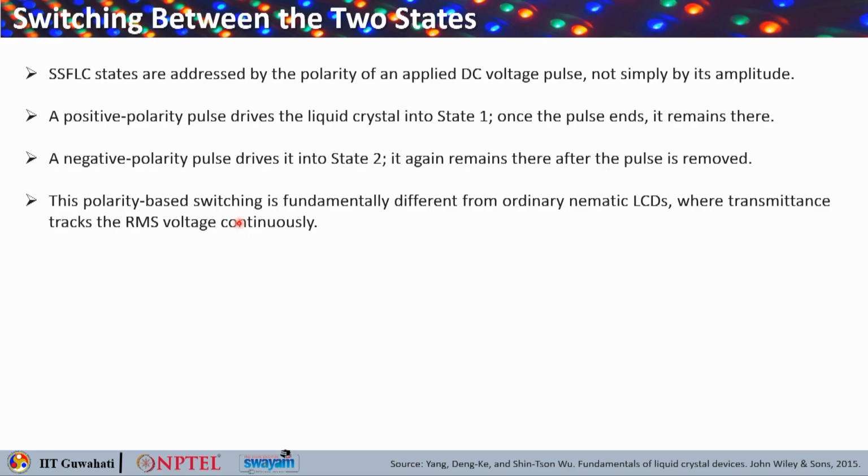So, this is basically polarity-based switching, not amplitude-based switching, okay, and this is fundamentally different from the ordinary nematic liquid crystal displays, where you will see the transmittance basically tracks the RMS voltage continuously. However, here it is basically based on the polarity.